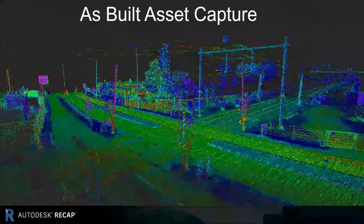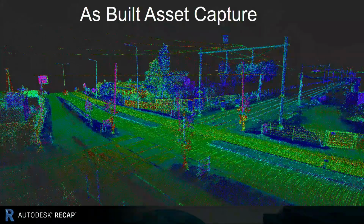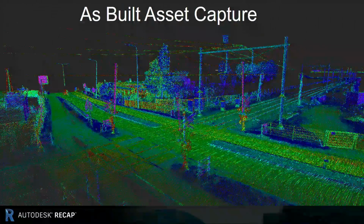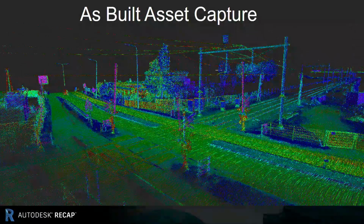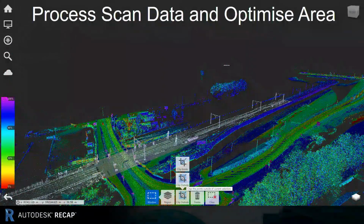So this is the reality capture in Recap. And what we're seeing here is the laser scan, obviously in Recap, all the points have been indexed, and currently we're presenting this with point intensity. And the idea with that is you can clearly see the rail lines have shown up in a much higher intensity. I can then move forward and then start to isolate that rail corridor. So you'll now notice in the rail corridor here, we have just the strip isolated there.